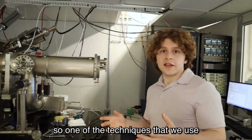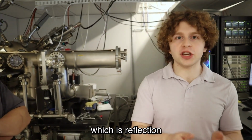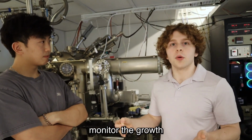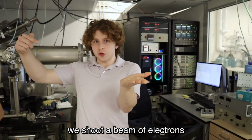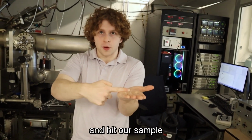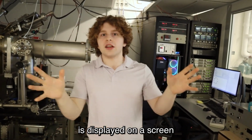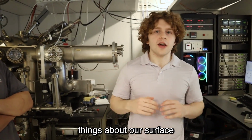So one of the techniques that we use for molecular beam epitaxy that makes it special is called RHEED, which is reflection high energy electron diffraction. RHEED is really important because it allows us to, in real time, monitor the growth that's going on. And so what we actually do is we take our wafer, right, if my hand's the wafer, we shoot a beam of electrons at a very grazing incident angle, so like a couple degrees, right? We shoot this beam of electrons and hit our sample and it diffracts off. And the diffraction pattern that's created by the electrons is displayed on a screen. We take pictures of that.